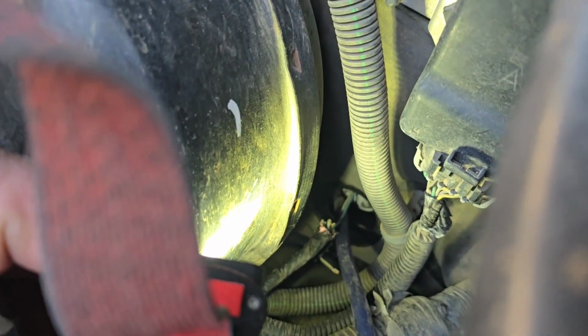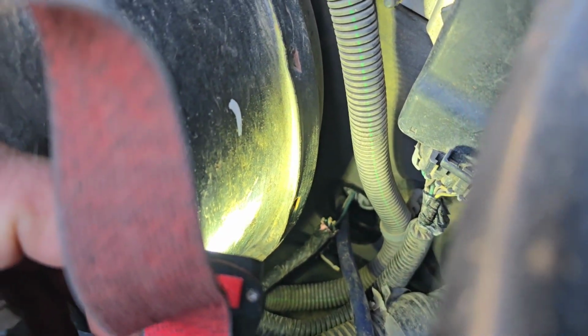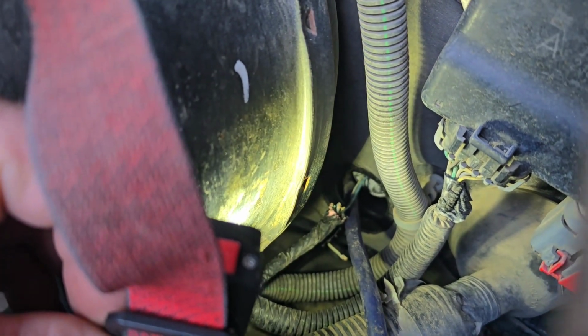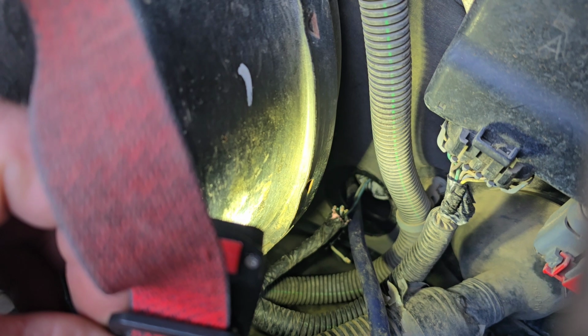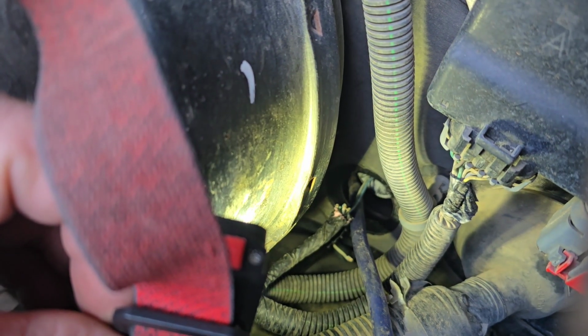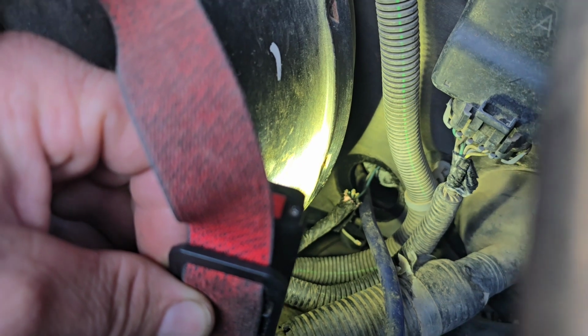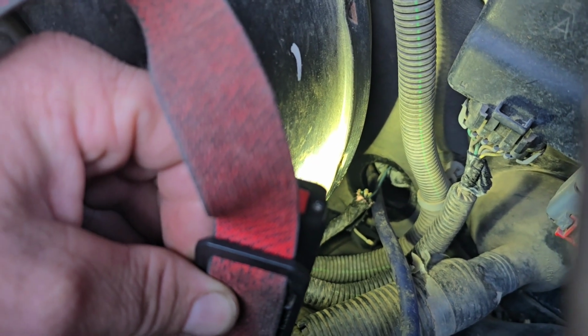So the repair, for me, I'm going to pull these out, connect to those 7, send them all through the grommet, cut a little slit in the grommet, and try to get it so that it's not an open hole so the mice aren't so tempted to go in there, but at least just make the connection.